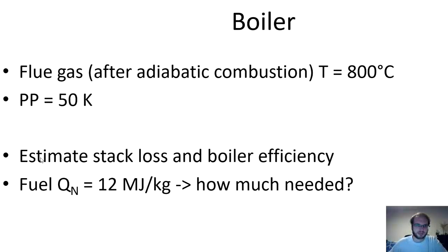And what we will want to do is to estimate the stack loss and the boiler efficiency. The stack loss is the loss of the heat in the exiting flue gas, because as you will see we cannot cool it down to the ambient temperature, and how much fuel we needed if we have the fuel with the lower heating value of 12 megajoules per kilogram.